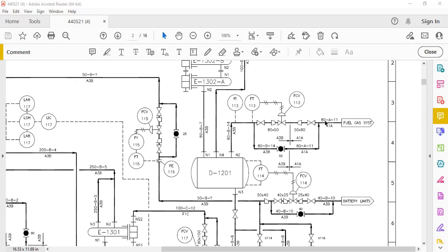Another thing is that there are two gate valves. Though it is already an automatic flow control valve, controlled by the FT flow transmitter or some control station, it will be controlled automatically. So what are the other two valves? They are manually operated, and they are for blocking. Whenever we have to change or do something in the control valve, we first have to block these two gate valves. We have to operate these two valves.